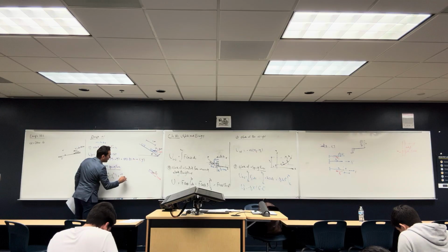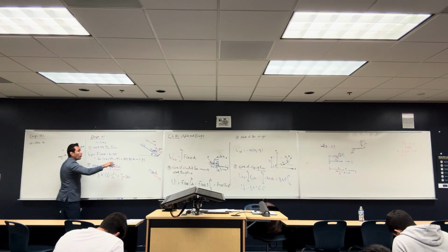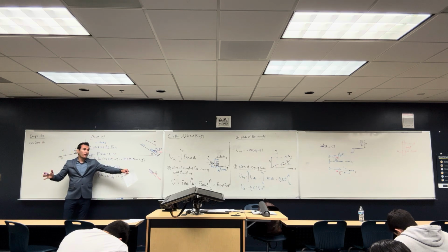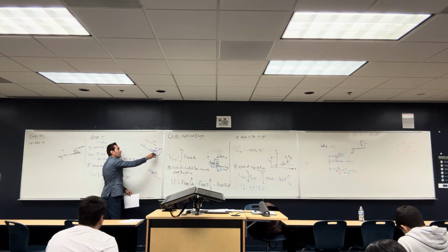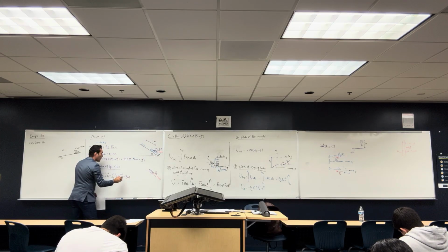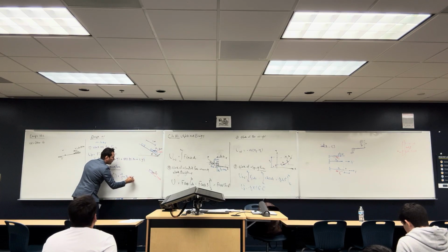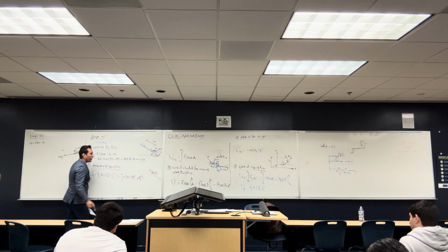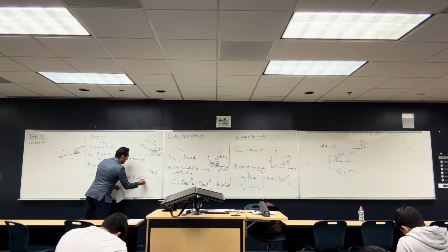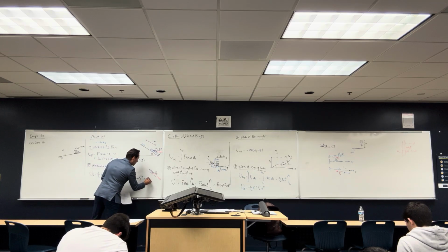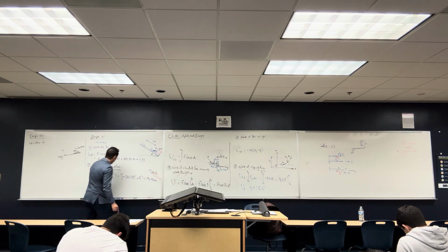I gave you that K of the spring is 30. I told you it was stretched 0.5 and then you pushed it another 2 meters, all in the same direction as the spring movement. So the final stretching was 2.5 squared and the initial stretching was 0.5 squared. When you solve this, it gives you negative 90 Newton meter.